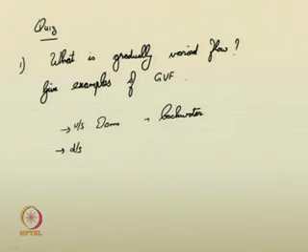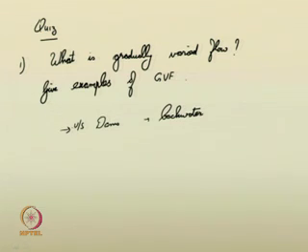In the downstream, or in channel steps, wherever there are step beds, where the bed of the channel is made in step formations, you will witness gradually varied flow, where the depth of the flow gradually reduces before it reaches the edge of the step. So, those are some of the examples.